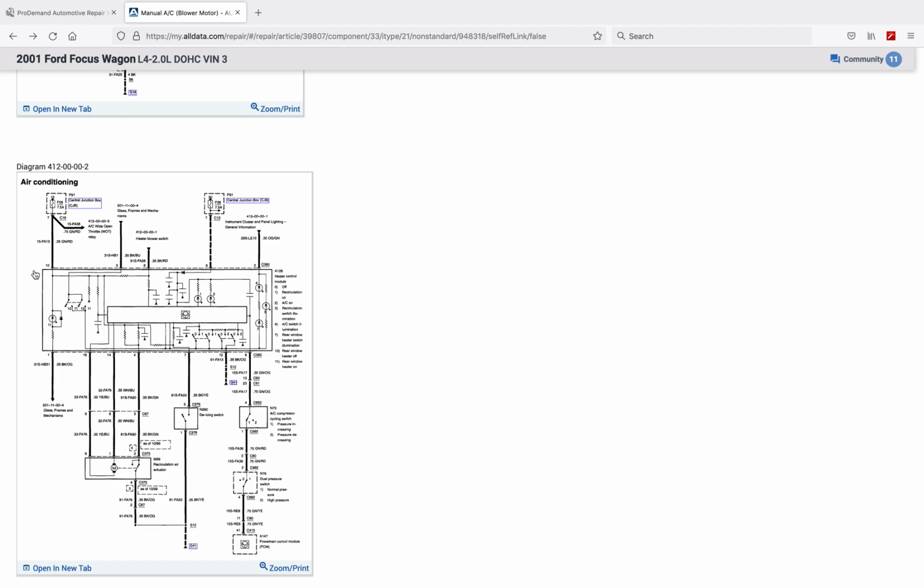First thing I want to throw out here, this module, notice there is a solid line around this module. That means you replace the whole component and not subcomponents. What I do have to call out though is that there is a dotted line between these numbers, all of these listed through here. What that dotted line represents is that we have more terminals. These small numbers are terminals. That's terminal 2, terminal 8, 6, 3, 10, 1, 16, 14, 4, 7, 12, 9.